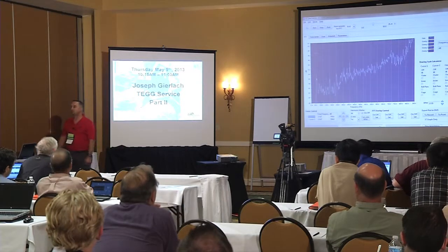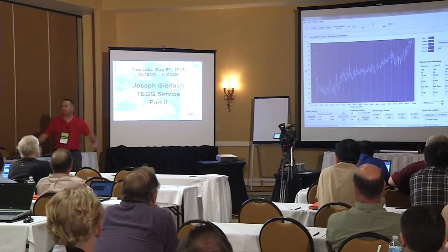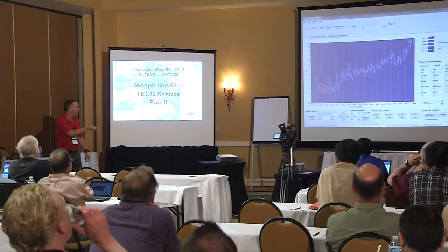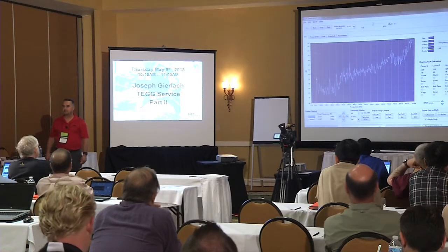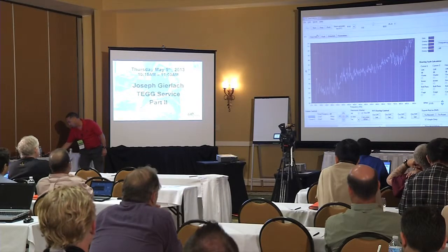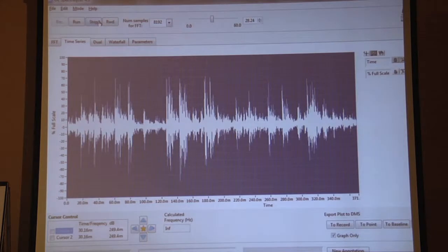It's electrical. We have several 60 hertz peaks, and we've got that noise content in here, right? We know it's electrical. If I go to the time analyzer, well, I don't even need to change that view, do I? I can already visualize what's going on just the way it's set here, can't I?